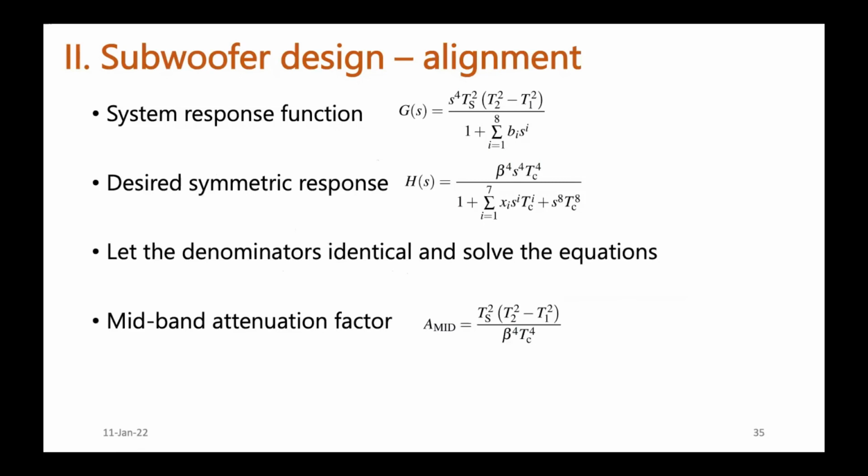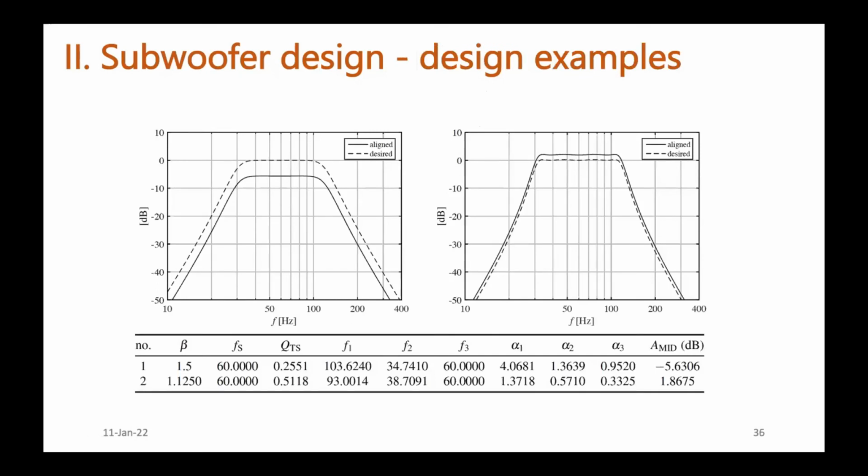It's quite long, and the system response can be aligned to the desired symmetric response given here. In this case, we don't need to factorize the denominator, just solve the eighth order equation set. And again, we can get the mid-band attenuation factor. It's important.